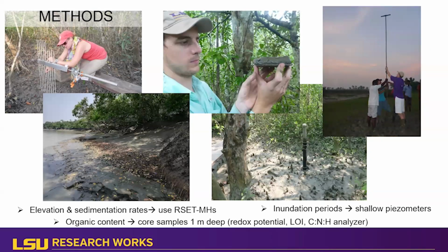My student, Jeff Bomer, and I used both surface elevation tables and marker horizons to get at some of the elevation dynamics, to look at inundation periods. So we were very interested in how much or how long the platform is being inundated. So this is hydroperiod, so that's a duration and a frequency kind of equation. We're using some shallow piezometers that are screened both at the surface and also within shallow groundwater. And then also took some core samples to about a meter depth.